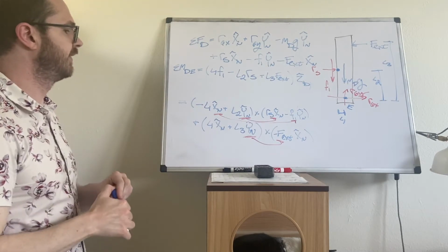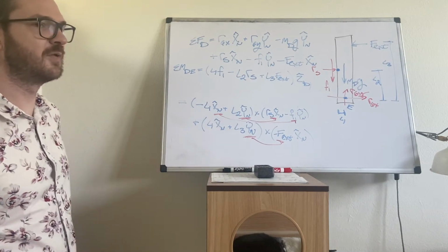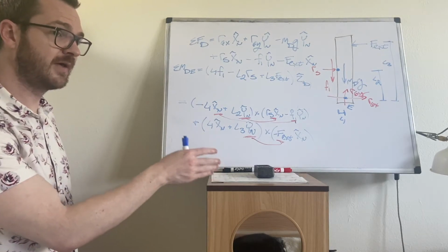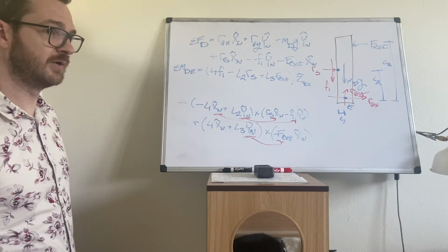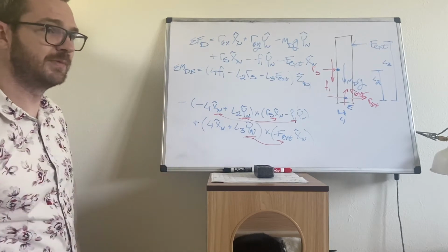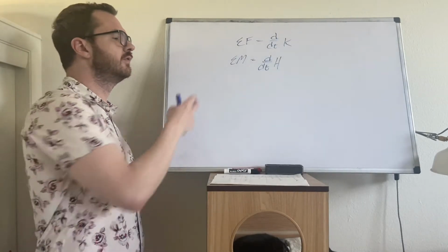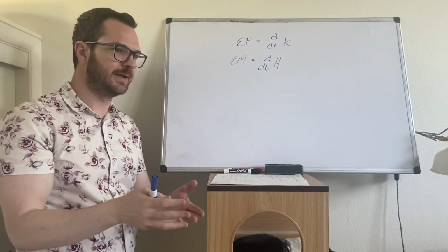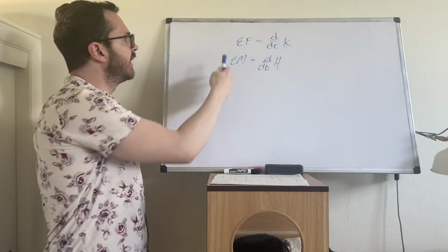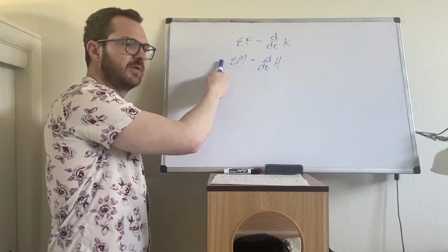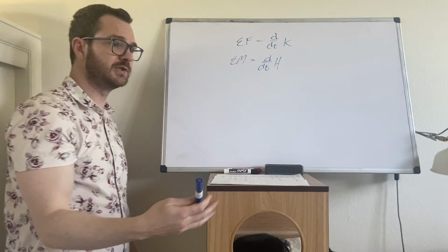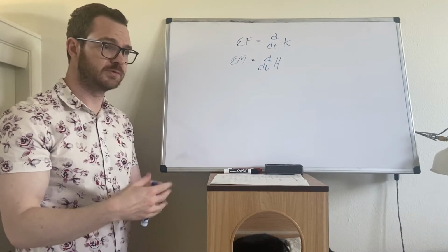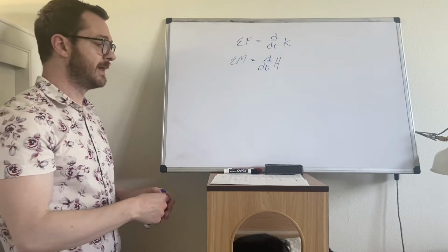All right. So there's sum of forces and moments for everything. We have kinematics. We have sum of forces and moments. That means we can get started now with the equations of motion. Let me clean it up. We'll get going. We know that we need to use Newton and Euler's second laws, but where do we begin? We have 4 bodies, and we could do sum of forces and sum of moments for each of the bodies. So 8 equations. We said at the beginning, though, the system only has 1 degree of freedom, so there should, at the end of this, only be 1 equation.